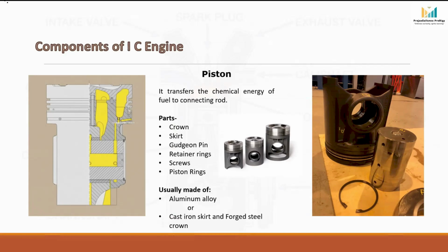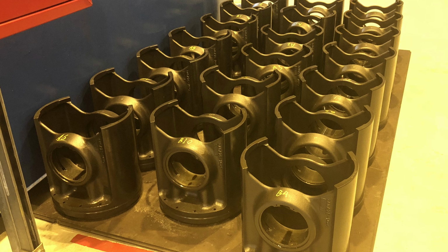If the oil ring fails, oil could enter the combustion chamber, which may result in higher oil consumption and exhaust smoke. The lower portion of the piston is called the piston skirt. We can see here, the piston skirt guides the piston during the up and down movement inside the liner. The skirt also absorbs side thrust forces, which are generated by the angular movement of the connecting rod.